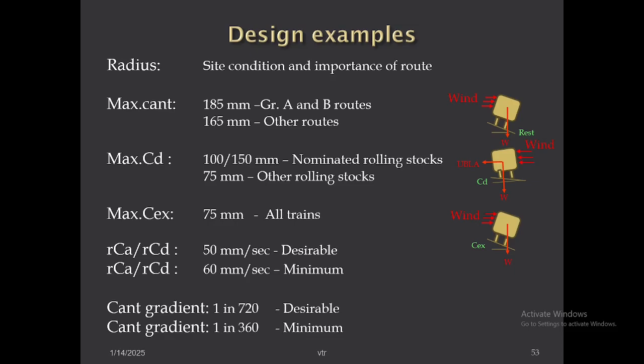Passenger comfort also has to be considered. When the train is stopped on a curve, the passengers sitting in the train will feel some discomfort. They may lean slightly towards the inside and have to adjust themselves. These are also some of the reasons for which we are compelled to restrict the maximum cant on the curve.